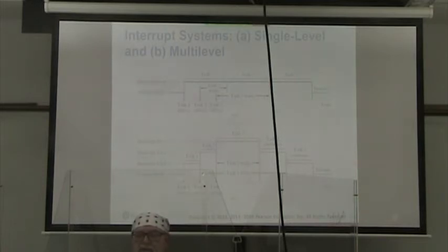When task 2 arrives, it waits until task 1 is done right here. Task 3 has arrived also in the meantime, but when task 1 is over, task 2 starts. Task 3 continues to wait until task 2 is done, and then task 3 is done, and we're back.